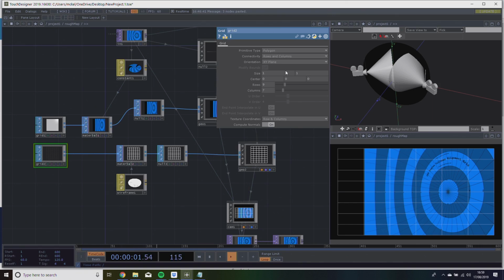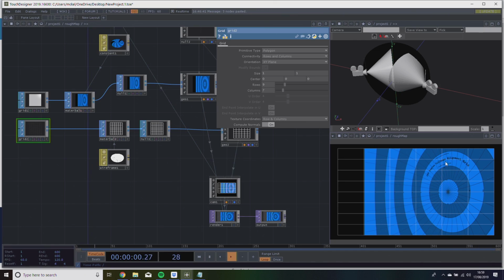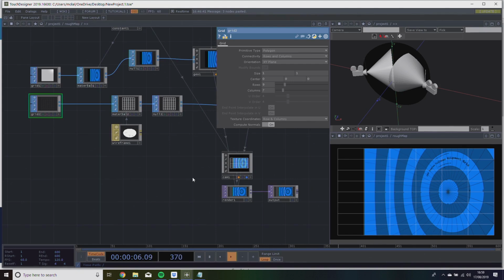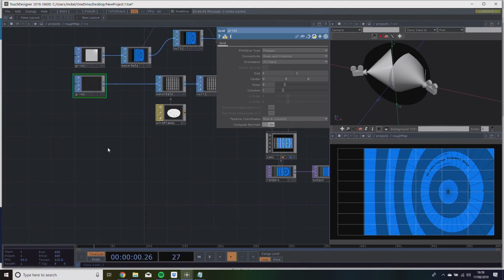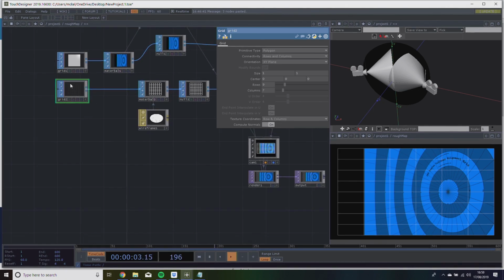Okay, so now we've got a super high density mesh, and we've made a lower density grid on top of it. What we need to do is create points on that grid that we can go and grab. So we'll do this bit, and then we'll take another 5-minute break, and then we'll move on to actually manipulating this grid. We're going to use a little bit of geometry instancing to allow us to create all the points without doing any hard work. But the first thing I need is a list of all of these points, make them a table, and then make a copy of that table so that we can properly send references back and forth between two different SOPs.